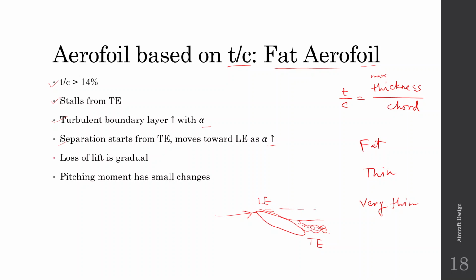But in this case this is good, because the loss of lift is very gradual, and the pitching moment also has small changes. So with respect to loss of lift and pitching moment, this is a good kind of aerofoil because there is no abrupt loss of lift.